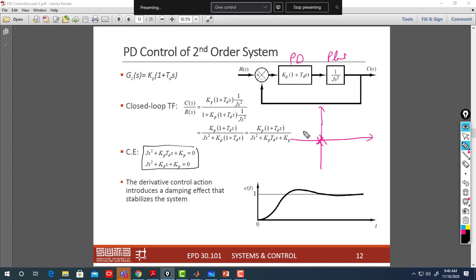closed loop poles. So then it's you, the designer, who changes Kp and Kd, or Kp and Td. You can put them in your desired location, depending on your desired response and your specification. Which settling time you need, which overshoot you need, which maybe omega n you need. If you know your overshoot and your settling time, you know where to locate your poles.